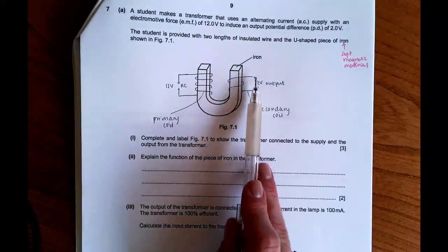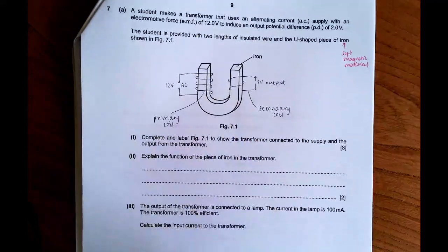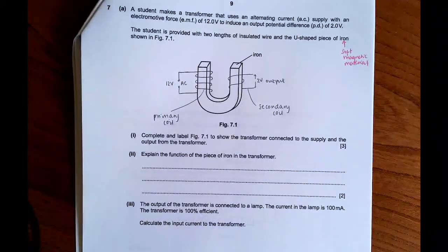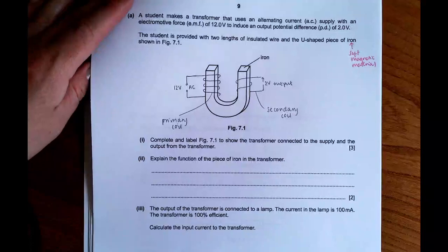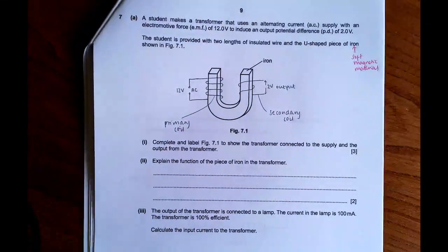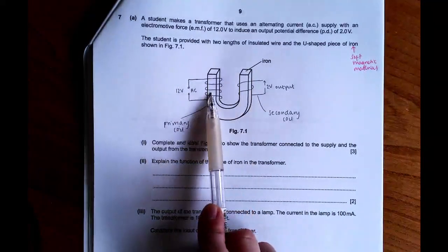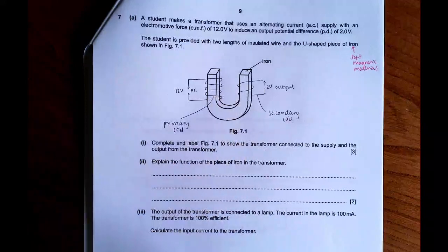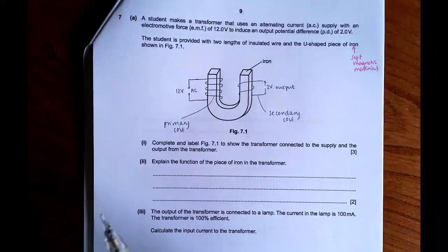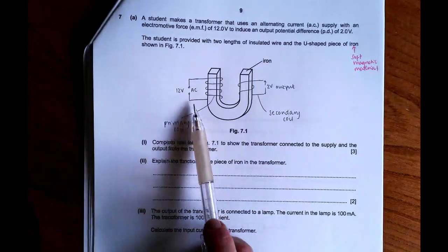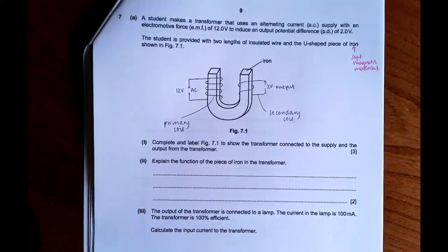And then I have a secondary coil which only has 2 turns, and that has been connected to the 2 volt output. You just need to say that it's a 2 volt output, you don't need to add a circuit in there. You're going to get marks for clearly having a primary and a secondary coil and there being a difference in the number of wires on each side. If they're the same, it's not going to be a transformer. You'll get voltages the same on both sides. So please make sure that you clearly have a different number. Then you need to label it, and it also needs to be wrapped physically around the iron. And they will be checking for all of those things.